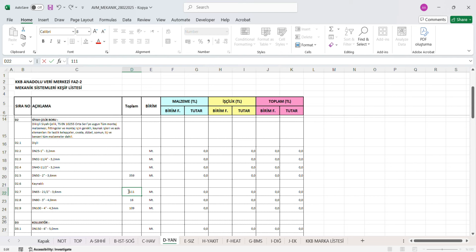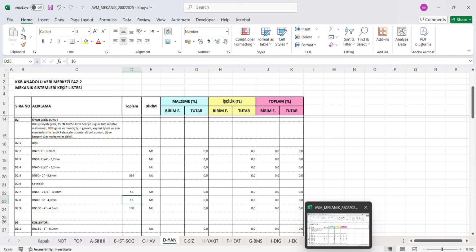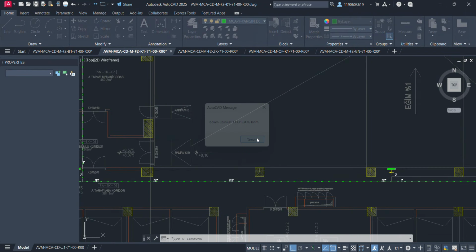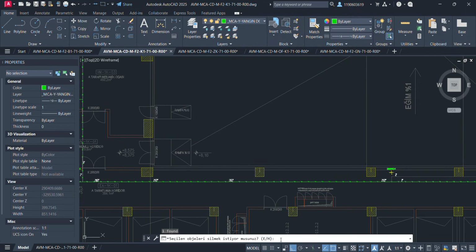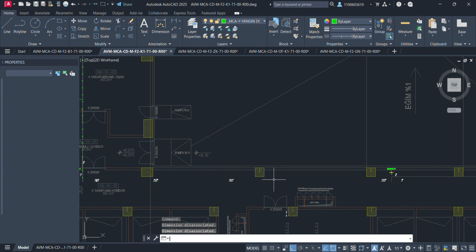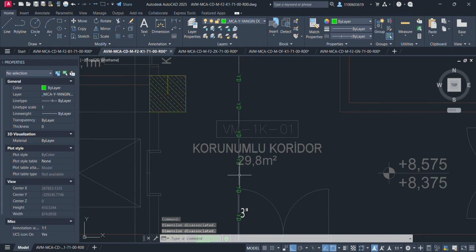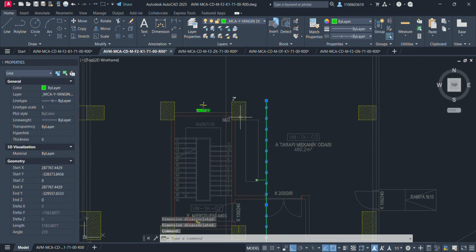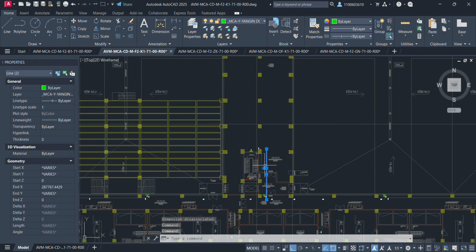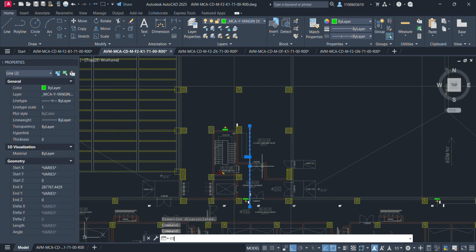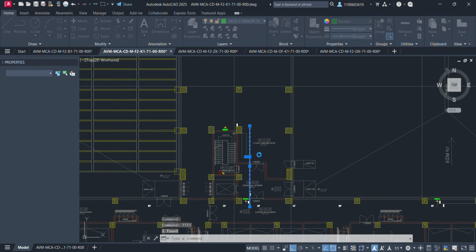Advantages of the system. Rapid response: the sprinkler extinguishes the fire quickly before it can spread and cause severe damage. Heat control: the system helps to reduce the temperature in the fire area. Self-protection: the system operates automatically without the need for human intervention. Maintenance and testing: sprinkler systems must undergo regular maintenance and inspection to ensure they function properly. This includes testing sprinklers to verify that thermal links are intact and that pipes are not blocked.